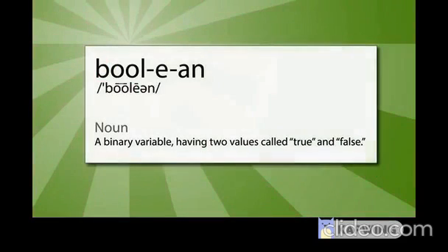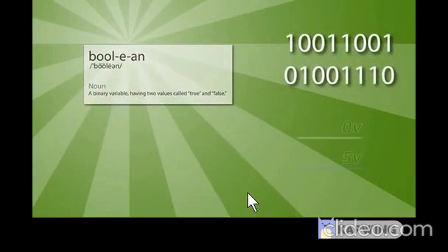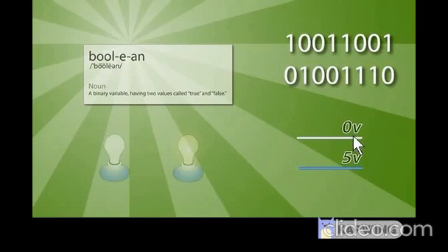But the maths a computer or an electronic device understands is very different. It is called Boolean maths, which is basically binary variables and which has only 2 values, because machines do not understand all these numbers. Machines only understand 2 values. Either there is a voltage applied to them or there is no voltage applied to them, right? So they only consider 0 and 5, and 0 represents 0, and the 5 volts, when a voltage is applied to them, is considered as 1.